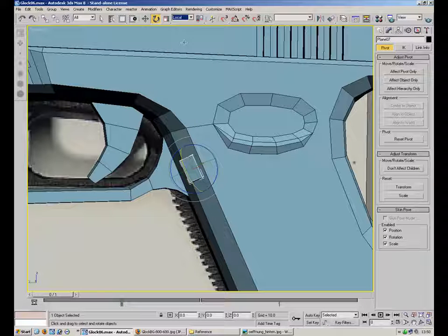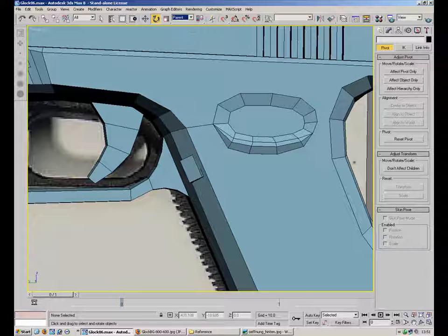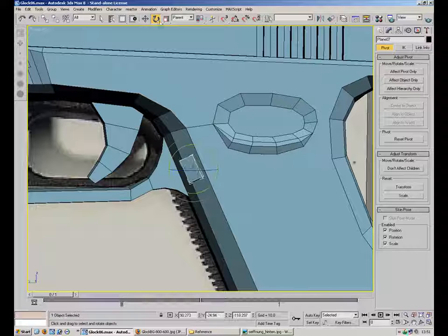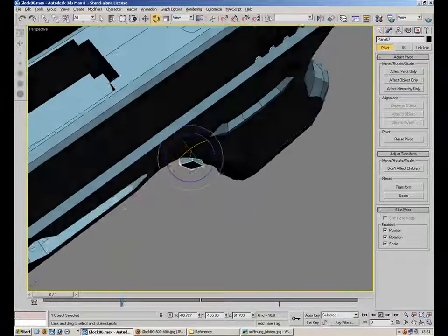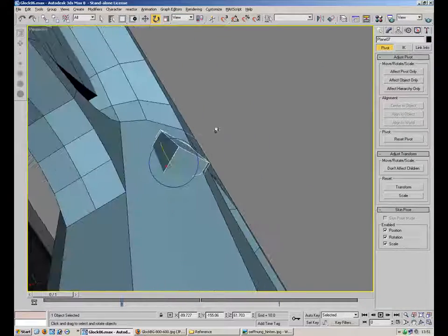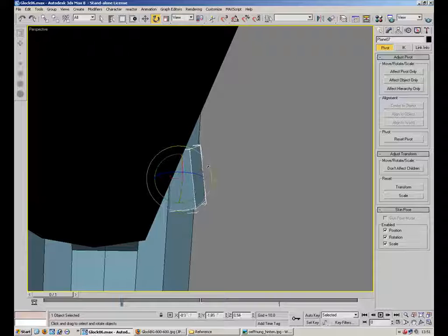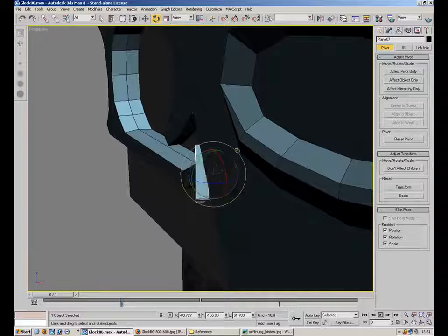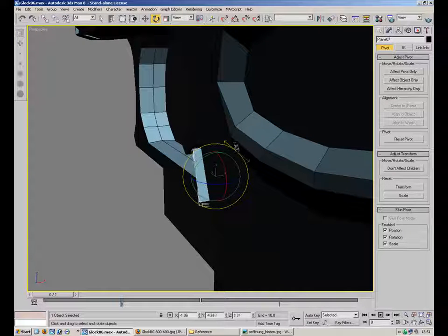If I put it onto local, it changes to the local pivot of your actual object, the X, Y, Z locations. Parent doesn't really matter, but that would be of the parent bone. World, I think world is very similar to view, but the only ones you're really going to use are view and local. And the grey here, I recently figured out, is the rotation of your viewport.